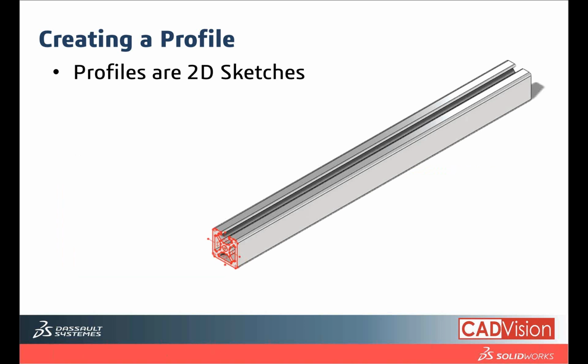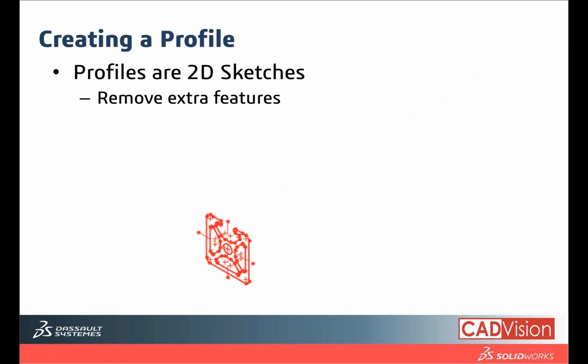So how do you do that? Of course, we know that the profile is always a 2D sketch. It's not a 3D model. So in order to do that, we are going to get rid of the features. Once you download the files, you can always right-click on your design tree and delete away your extrude features.